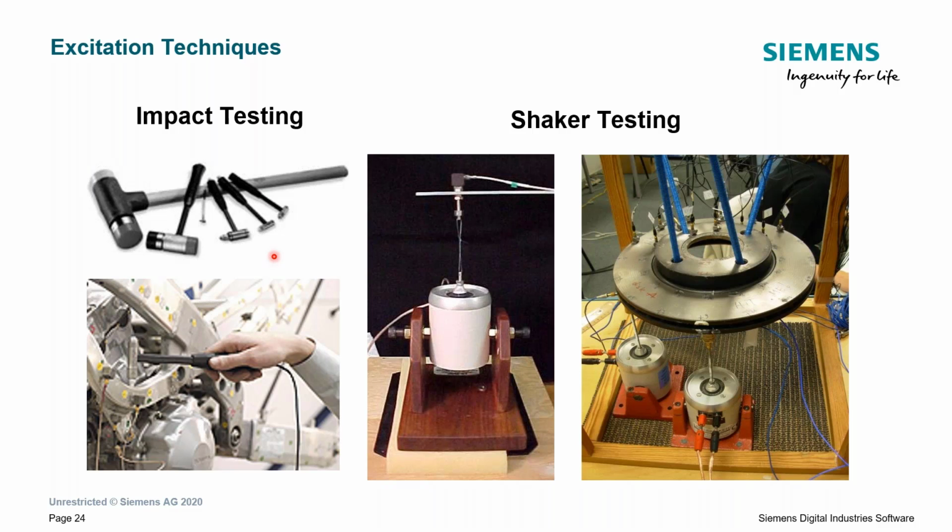But again, the larger the hammer, I cannot go as high in frequency. So with these two large sledgehammers, I won't be able to look out to a high frequency range. And we'll go through some things in the software to determine where we can look and the frequency range selection based on our hammer setup. We'll talk about that too.